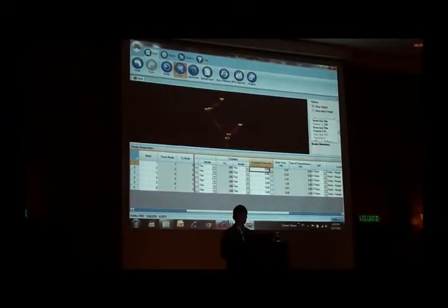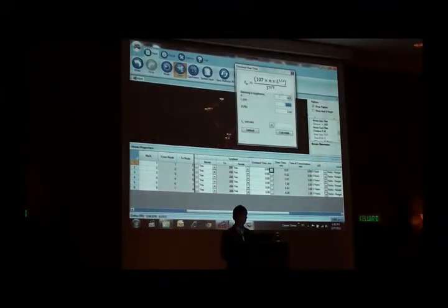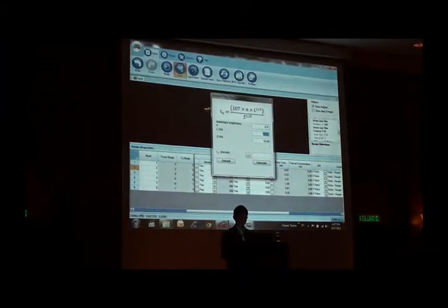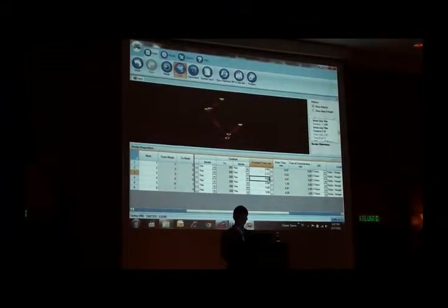Overland time, the T0. We can either key in the value or call out the calculator. We can see here the L and the S are ready. All this is picked up from the drawing, because we have the existing and proposed level inside the drawing. Then for the Manning roughness, we have to tell the program which surface type, let's say we choose concrete. So we get the T0, calculate, we get 3.5. The second one is also the same. We go here, choose, then calculate, 2.12. Or if we want to, we can also key in.